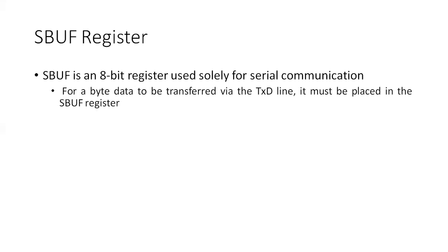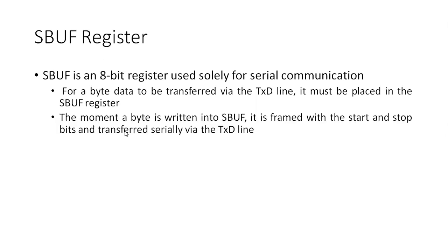For a byte of data to be transmitted via the TXD line, it must be placed in the SBUF register. The moment the byte is written into the SBUF, it is framed with the start and stop bit.